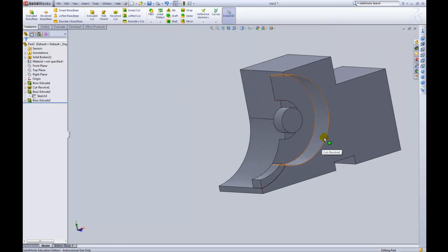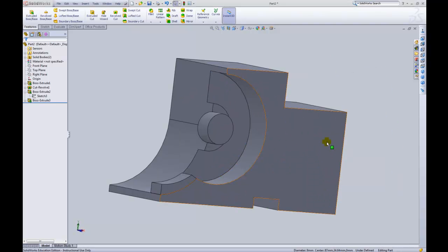Those were some of the more difficult parts. Now let's do the easy stuff. And I'm going to start with the hole that's over here on the right hand side. One of the issues with the hole is that it does not have a vertical dimension of its own. It shares a plane with the center of this feature, this feature, this feature, this feature, and this feature. Obviously, this is a very important plane for this to be on, so I think it's important enough to make our own new reference plane.